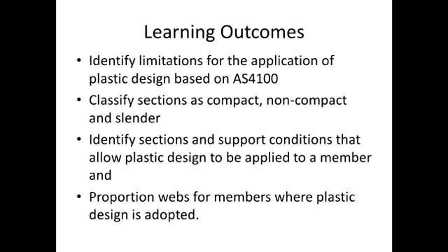So it also looks at some sort of B over T ratio, or in the case of webs, the height of the web and the thickness of the web, and then what the standard says in order for us to have confidence that if we applied loads to that beam, and plastic hinges were forming in a certain part of the beam, then we'll be confident to also use plastic design.